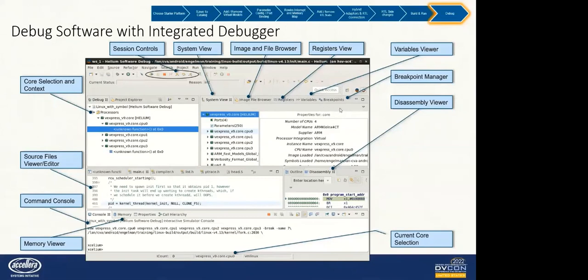This is the breakpoint manager where, during the software debug, wherever we are putting the breakpoint, probably in the C code or disassembly or in the outline or any function level, all the breakpoints that we have kept anywhere would be managed by this single breakpoint viewer, wherein we can enable, disable all the breakpoints from the single location. This is the disassembly viewer where all the disassembly level code we should be able to see during the software debug.